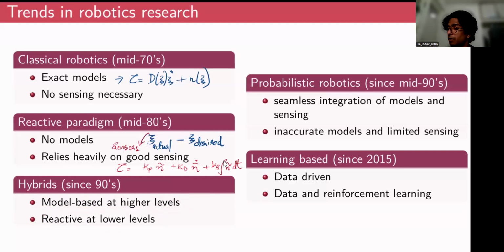For example, if you have a multi-link robotic arm and you want it to execute a specific trajectory at the end effector coordinates, you would want to know how much these joint variables should be moving. To achieve this final end effector position, you should be able to determine what the trajectory of each of these joint variables should be.